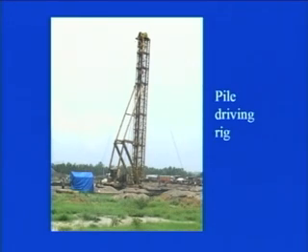But in the case of barren lands, you can see here that nearby there are no structures, only some trees and some barren land. So, that is why at this particular site they could go for these driven piles. And then when we were dealing with the person who was taking care of the construction of piles, he told us that usually in the case of driven piles, they go for 550 diameter in India.